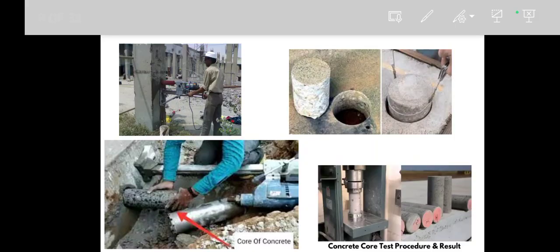When we use the ratios for M20 grade concrete for that beam member, we will additionally cast some cube specimens, around 6 or 3 based on the IS code, cure them for 28 days and test them in the compression testing machine. Based on that value they will give approval on whether that concrete has reached the target strength of M20 grade or not.